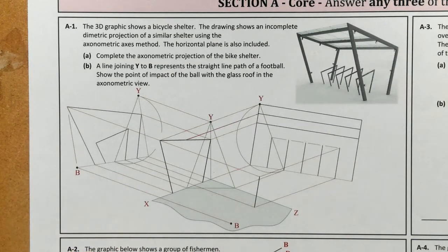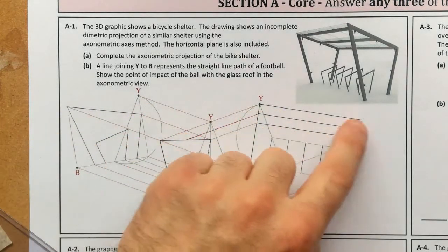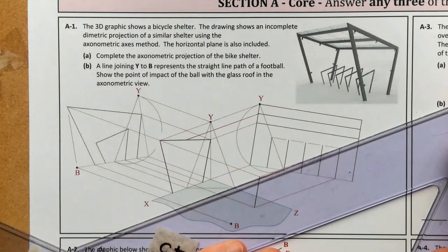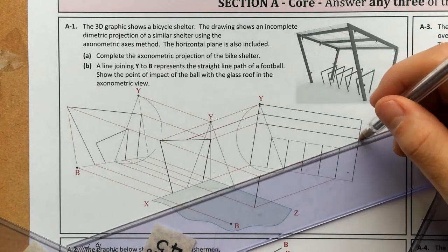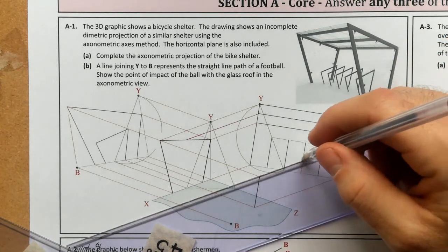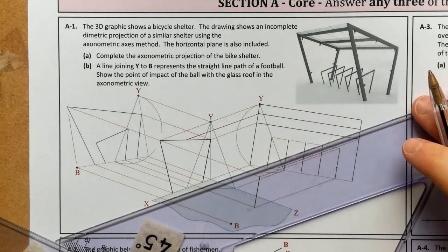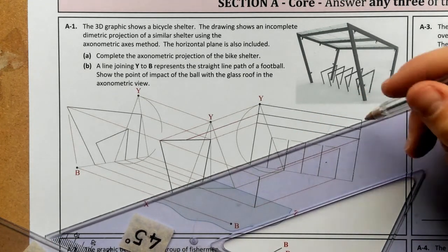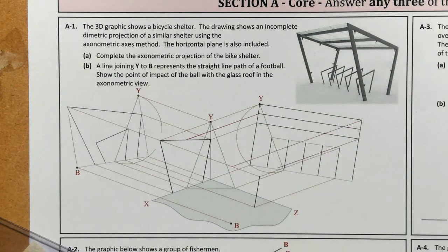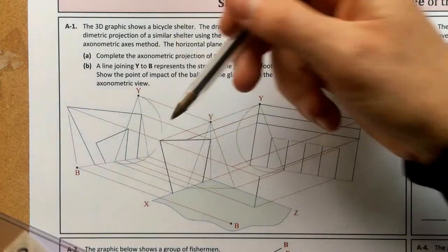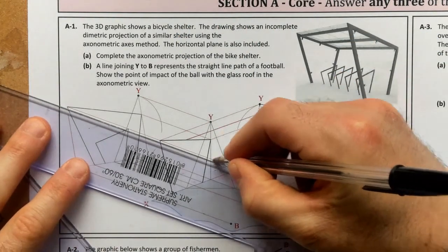Now I'm going to focus on the top surface of it first of all, this top face here. So I'm going to project down. It's just a case of working through it slowly, all of these points here. This one here, the lowest one, is actually at the back, so it'll be down there somewhere. Then it'll be on the top one as well. That top one has actually helped me out straight away, because I can see this one here is already there. So I'm going to heavy in that now.